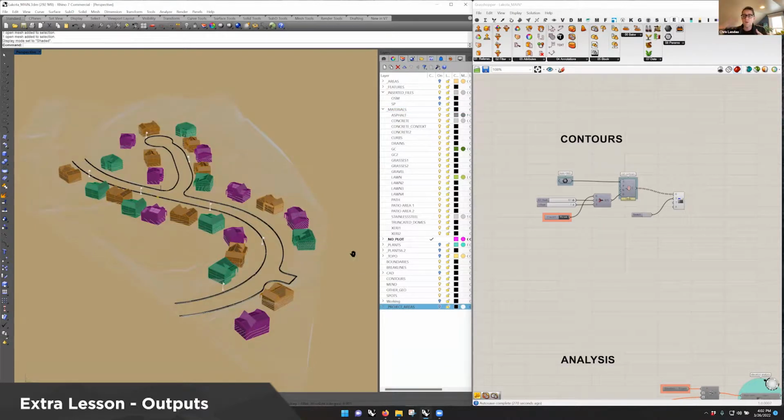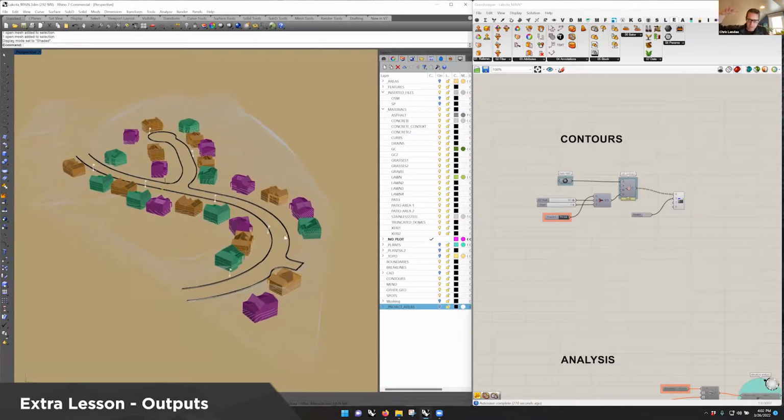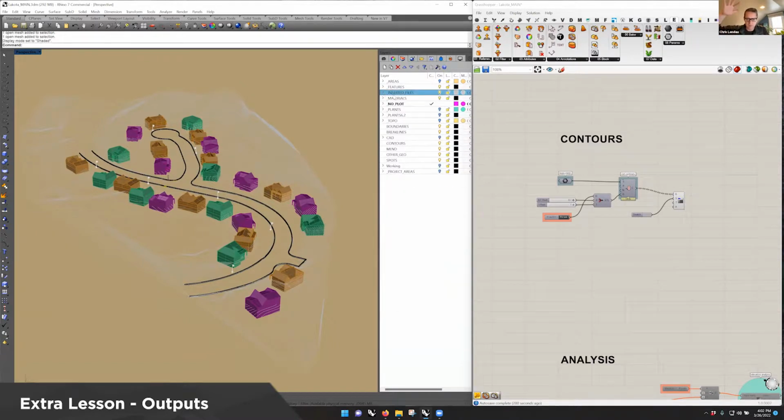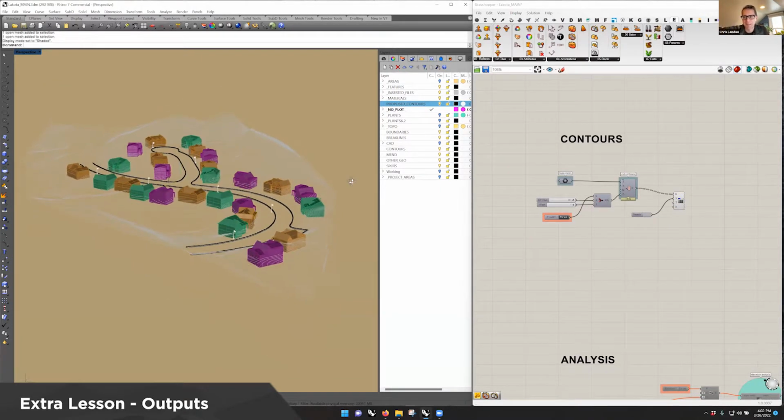The one thing we do stick with is the elevation of something, though. Like if all these contours are at whatever 1,000 feet, we keep them at elevation. Part of the reason is because whenever you go to export stuff, it's really great if something comes into CAD as something that's at elevation. So if somebody goes to label it, it's actually correct and at the right location. And Ben's actually going to pick up from there and talk about exporting contours.